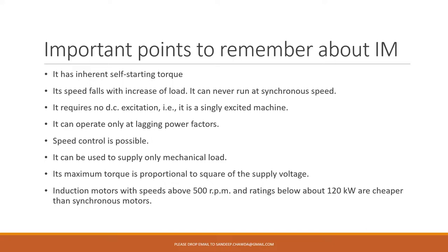When you connect AC supply to the stator of a three-phase induction motor, it starts operating. You do not need to provide excitation separately, and it does not require DC excitation. Therefore, it is a singly excited motor. Single excitation is enough; no DC excitation is required. This motor is going to operate only at lagging power factor.